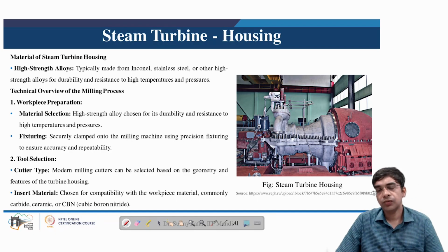In case of conventional machining, we have seen several processes in earlier classes such as turning, facing, drilling and milling. With respect to the steam turbines, it is the milling process which is very popular to develop the final shape with proper surface finish on the blade surface.